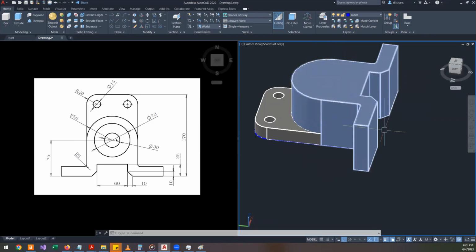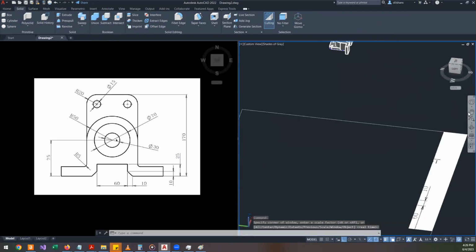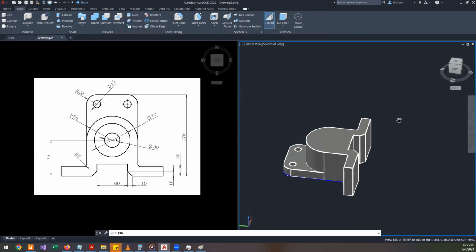Or otherwise you can draw a cylinder, so you can create a cylinder here, which means draw a circle and extrude it, then use this Boolean operation, subtract, to remove that cylinder. Okay, whatever you choose is correct. So both techniques are correct. I'm going to follow the easy path, which is basically to draw the circle here and use the press pull command.